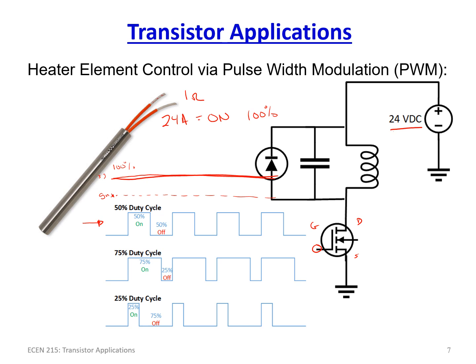Now, if I have a waveform, say that this is a 1 kilohertz digital waveform, it's a square wave. And this right here being 1 kilohertz, that means that this is 1 millisecond. And what we call 50% duty cycle is dealing with pulse width. Duty cycle represents the amount of time on versus the amount of time off.